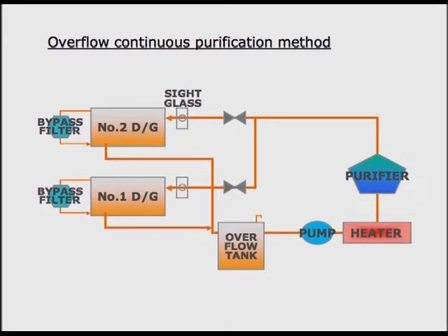Continuous overflow cleaning method allows you to curb the dirt level of the lube oil to a certain level because it is the method with its own tank and constantly cleans the lube oil during the operation. Transfer the lube oil in both the sump tank and overflow tank from the settling tank regularly to carry out the cleaning of the tanks.